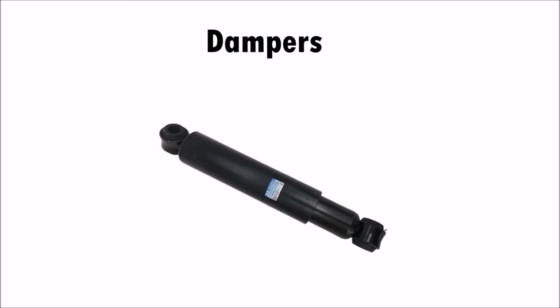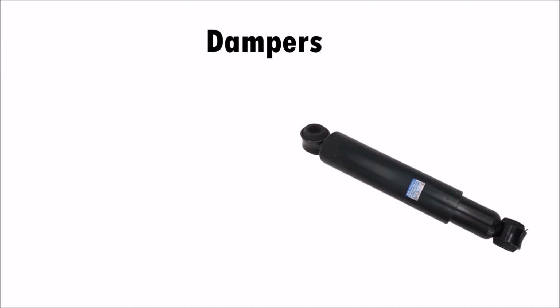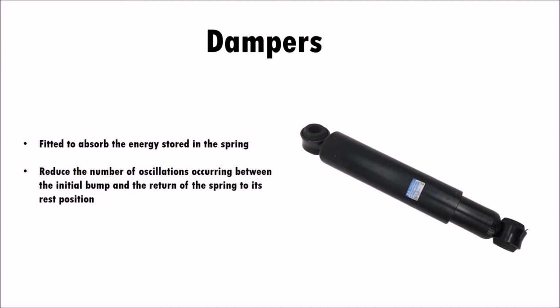The role of the damper comes into play when the vehicle strikes a bump in the road and the spring deflects and oscillates. The damper reduces the oscillations of the spring, thus improving the ride comfort and the road holding of the vehicle. It is fitted to absorb the energy stored in the spring.